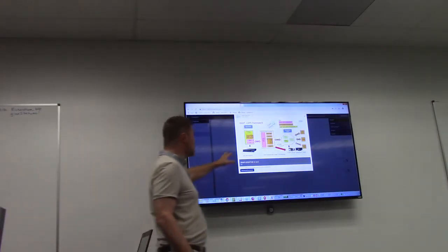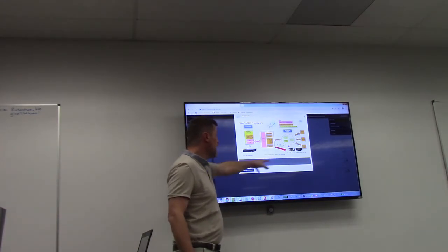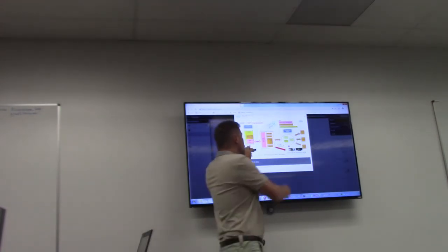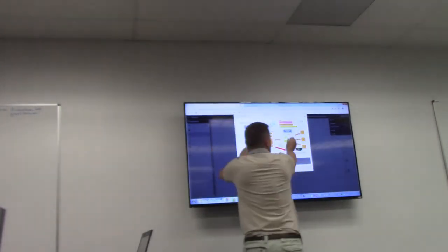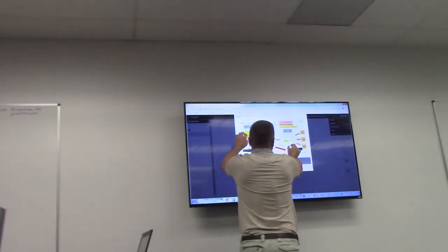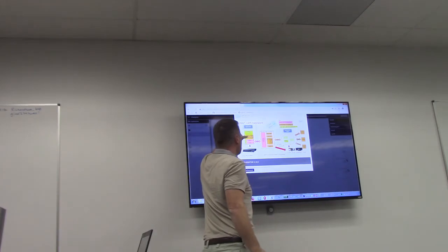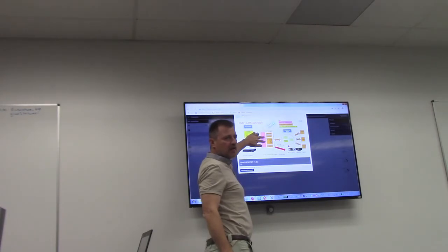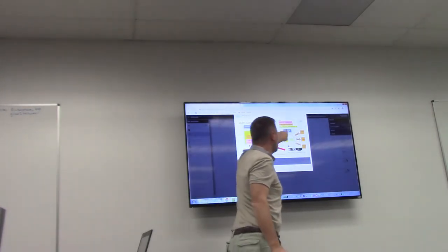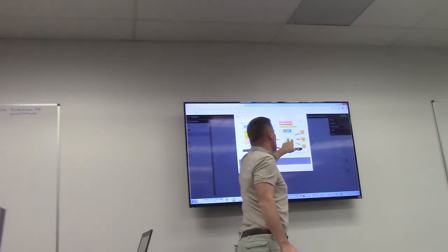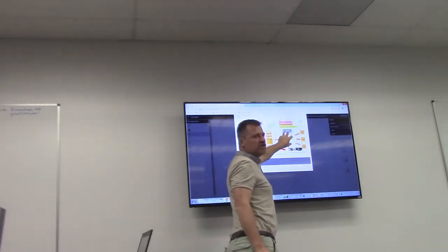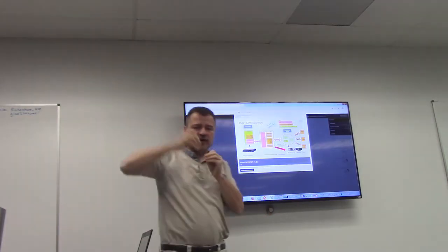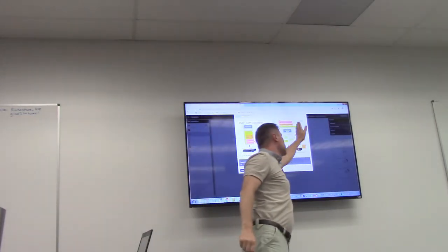I just recall the slide we have seen already, just for you to have in mind what we intend to do. We intend to take an application and to put a specific part of this application into the FPGA, like action 1, action 2, and we will use a specific snap library. We will use a specific hardware that IBM is providing in an encrypted file. The snap will provide all the connections for you, and we won't use the DDR on our example, because our example is just using the logic to catch the file. Remember this file that we want to change the case? We take the file, modify, and put the file back. So we don't use the IOs in our example.